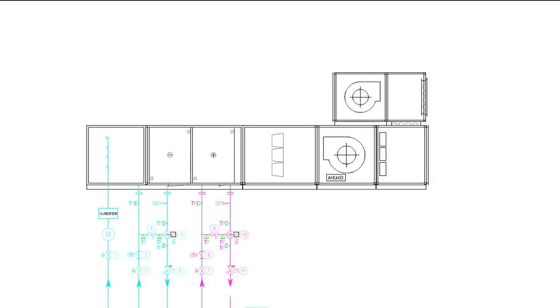Now, a schematic drawing of how an AHU will look is something like this. In this example, the air is flowing this way, through the filters, and the fan is pulling that in. You've got the bag filters there, and then it passes into the heating coil. You can see that because it's a plus, because it's adding energy into that stream of air. Next, it will pass directly into the cooling coil, and you see that because it's got the negative, because it's taking energy out of that system.